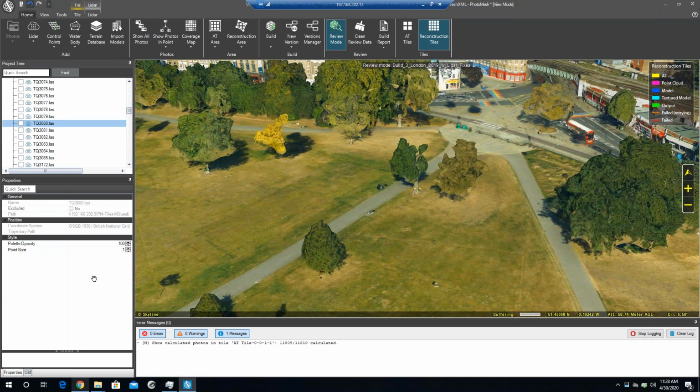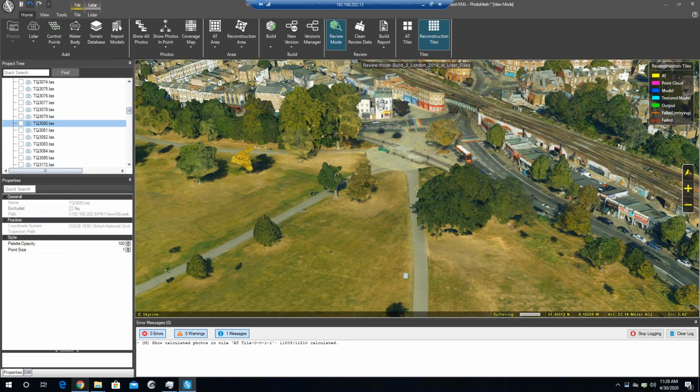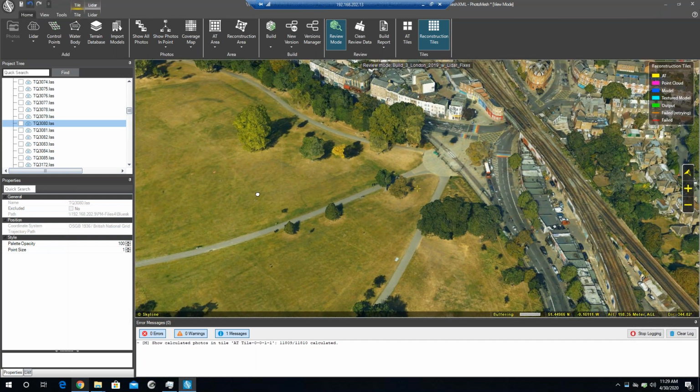to take precedence. We do give a little bit more weight to the LiDAR points under the assumption that the LiDAR points are more accurate because they come from a ranging sensor, as opposed to an image correlation process, which has a little bit more leeway on the location of the point. So the LiDAR does get more weight in the process, but some of the process does rely on having good